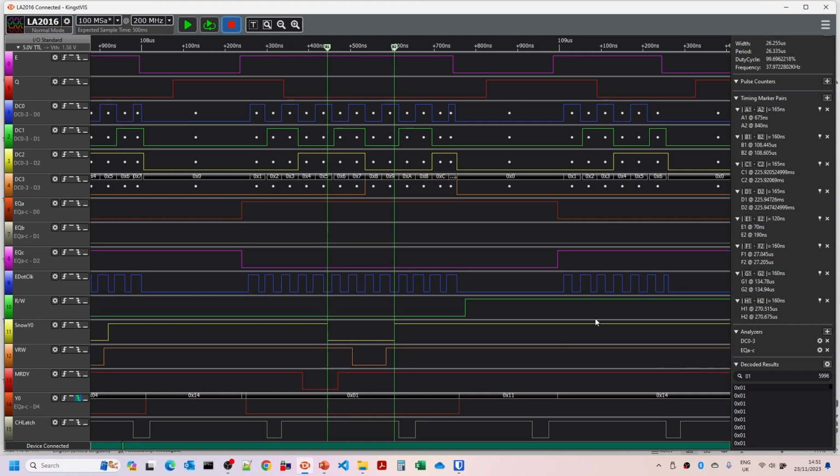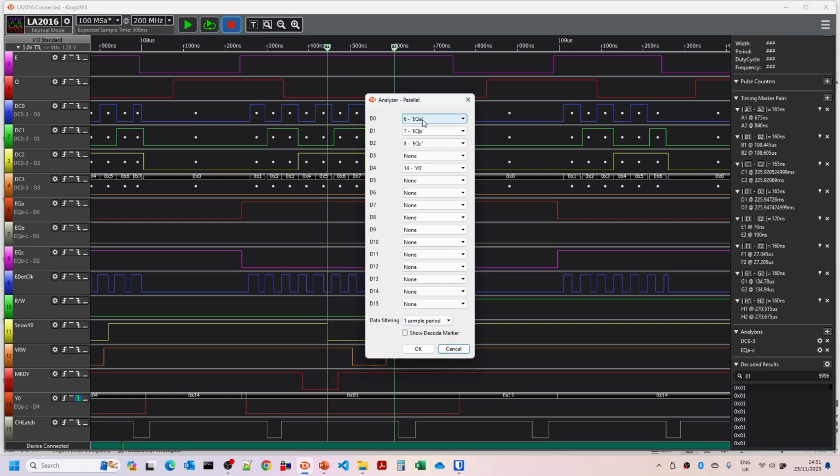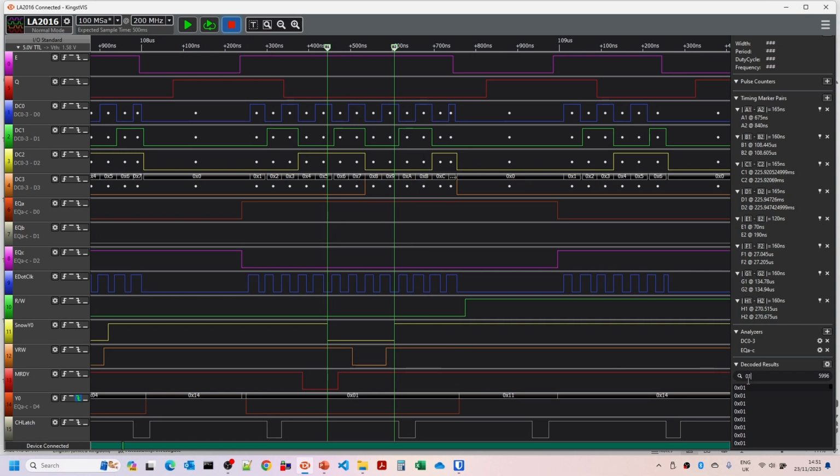And what I have done is for each of the clock cycles, because I'm combining the Y0 signal, so if we look at the decoding of the clock cycle of the CRTC, so that's the latched QA, QB, QC from the E signal, I've combined that with the Y0 signal there, and what that means is we're only interested in when that value is 0, and so anything which is with a leading 1 we can ignore. So you can see here that all these ones with a leading 1, that's when the video RAM is not being accessed by the CPU.